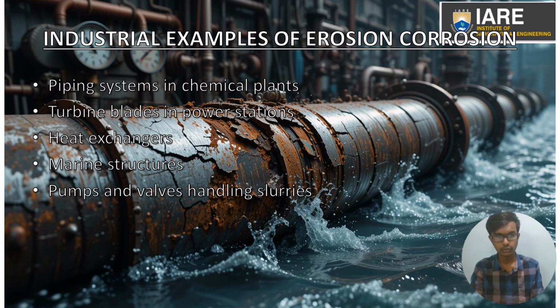Now let's quickly go through the industrial examples of erosion corrosion. Firstly, piping systems in chemical plants. These piping systems often carry a high velocity corrosive fluid which strips away the protective film, leading to rapid metal loss and leakage risks. And after that, turbine blades in power stations. These turbine blades are exposed to fast moving steam or water, and it causes mechanical impact and chemical attack, especially at edges and surfaces.